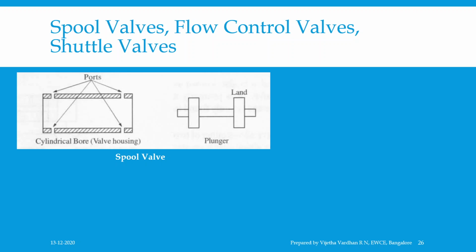Spool valves are more preferred because they offer extreme flexibility in interconnection through a simple sliding mechanism. They are also relatively simple and economic to manufacture. But the drawback is adequate sealing has to be obtained by fine surface finish on both the spool and the cylindrical boring, with closer tolerance to ensure minimum clearance to prevent internal leakage. In practice, spool valves are usually lapped to fit.